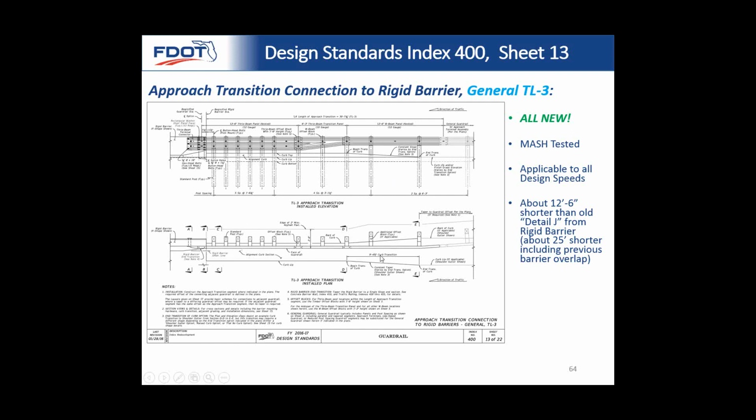If this was very soft and flexible, and then you had a rigid wall, a vehicle would get pocketed, basically go into a pocket and get snagged right here, and that's very bad, to have an instantaneous stop of a vehicle. So you want this to slowly gain rigidity.